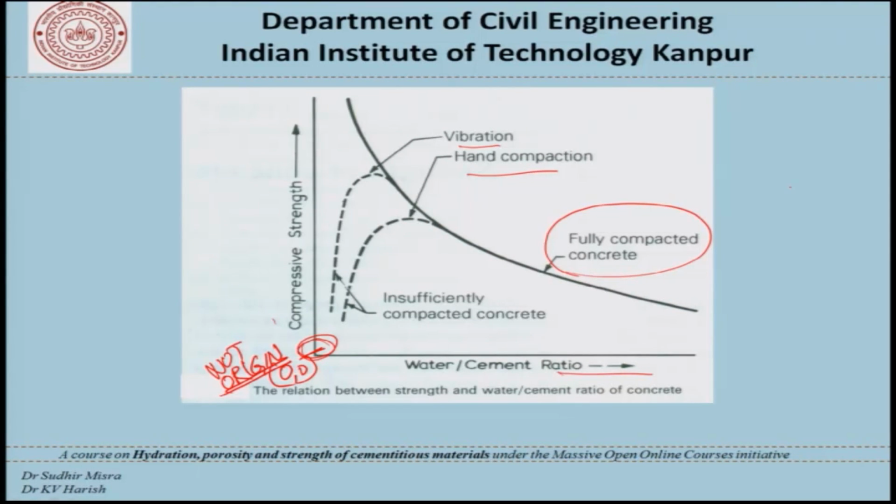What is the minimum water cement ratio from which we can say that the strength will go down as the water cement ratio is increased beyond that point? Below that point, as the water cement ratio increases, the strength is likely to increase, because what we are basically doing is providing at least some water, just enough water perhaps, for hydration to happen.